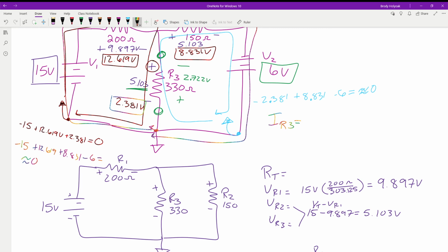Or just that one go around? Well, because when we measure it, we're going to be measuring to our ground. So we'll put our positive probe here and our negative probe there. So if the 6 volts, if this was dominant, we would have a negative voltage. When we went to measure it, we'd be getting a negative voltage across that piece. And again, the polarity is literally how am I measuring it? Which direction is current flowing type of a thing. And so when we hook it up to our meter, we want the common or negative to be closest to the ground, is the idea there.